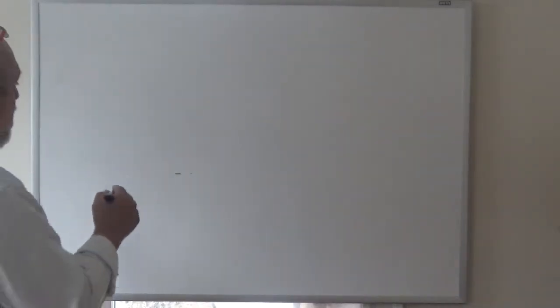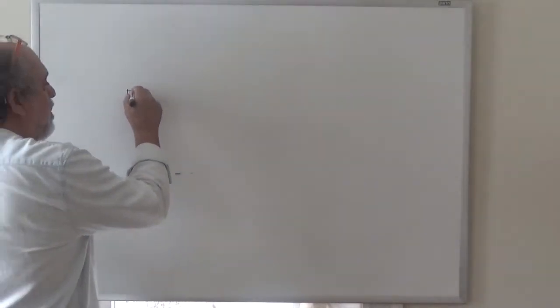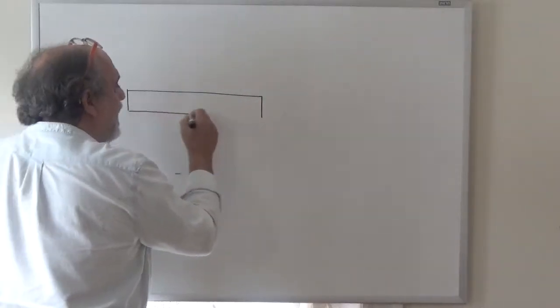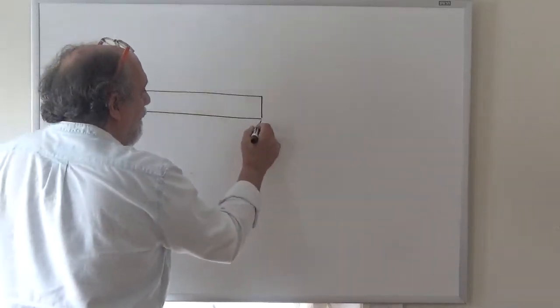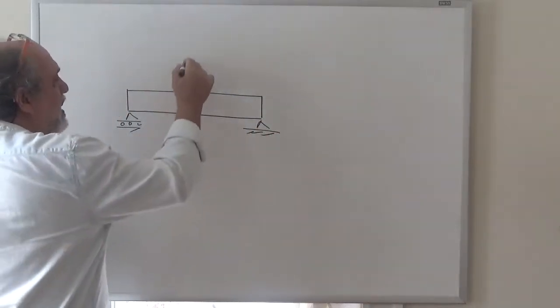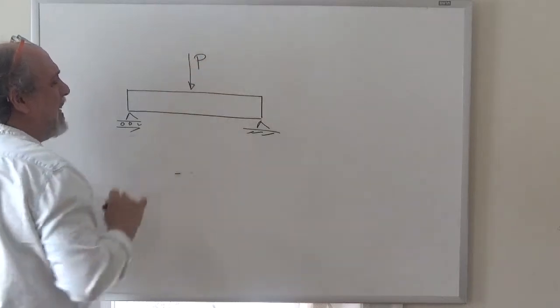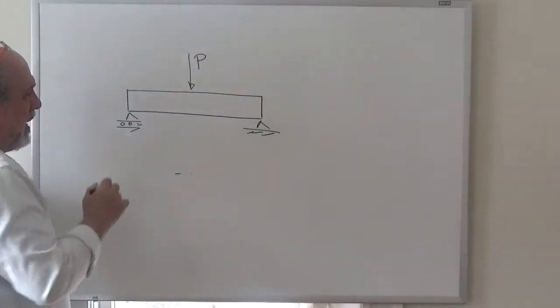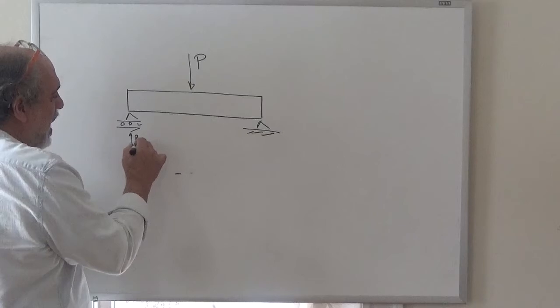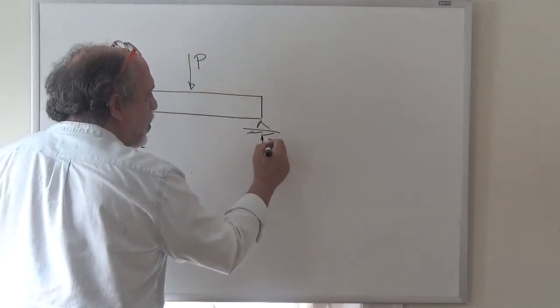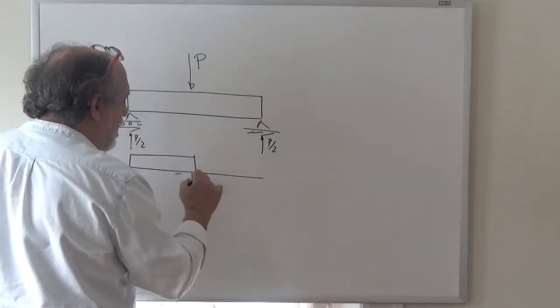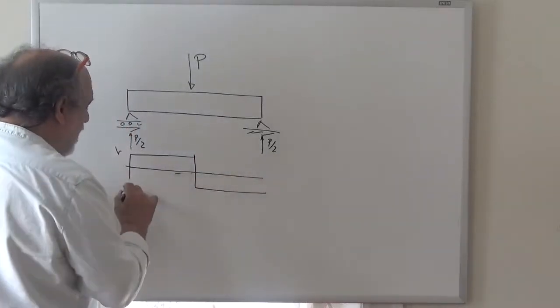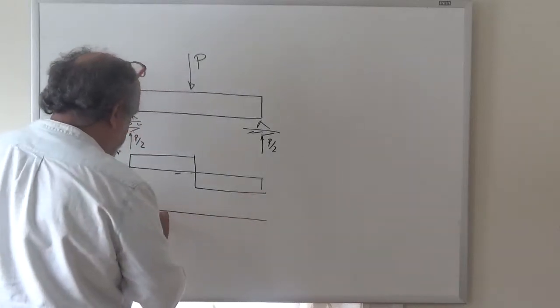Now, for those with a mind like the way I like to approach these problems, the static determinacy problem of applying it to structure is even a little bit more problematic than what I just said, because even if you look at the simple case of a simple beam, like this, you would say, wow, that's the most statically determinate situation in the world, right? I can calculate these two reactions right away by looking at it. They are P over 2. I only needed statics. I can do my shear diagram from statics. I can plot my moment diagram from statics.